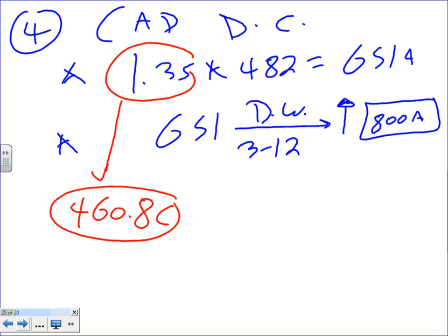These two tables are for a 480 system. If you're using 208, way at the bottom, it says for maximum benefit, located at the motor for a 208 system, use 33% larger. They're saying right at the bottom, guys, these two tables are for 480 system. If you are to size it for 208, which is not common on major motors, you really want them to be 480.